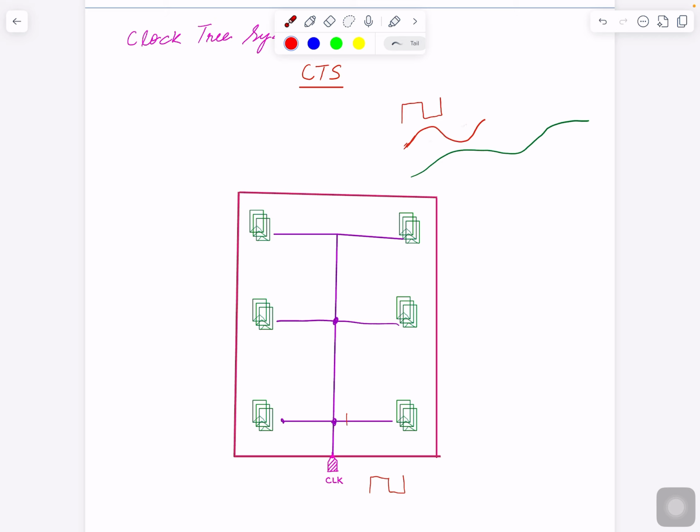And the drawback, you know that eventually the edge is used to capture and launch. But the definition of edge becomes harder and harder. Eventually it will become very hard to distinguish between 0 and 1. This will kind of stay in the same logic. You see, this will be catastrophic for your synchronous design. Synchronous designs work on clock. Clock is what synchronizes data, what times data. Based on that, you perform a lot of other actions in a certain timely manner so that you don't create a catastrophic situation. Instead, you properly manage or propagate data from flops to flops. Okay, so you understood why we don't want this?